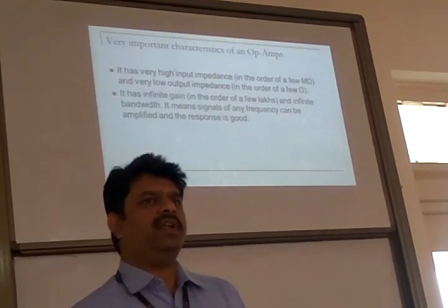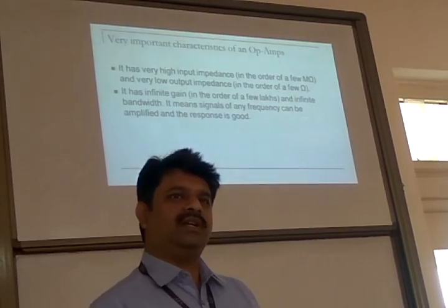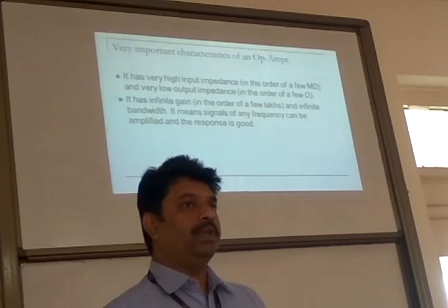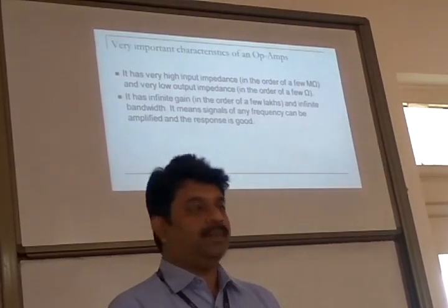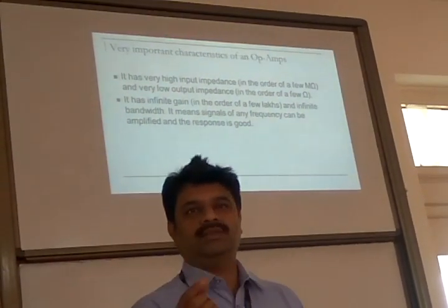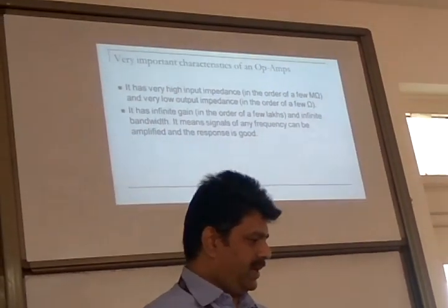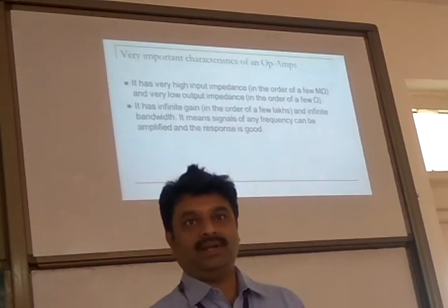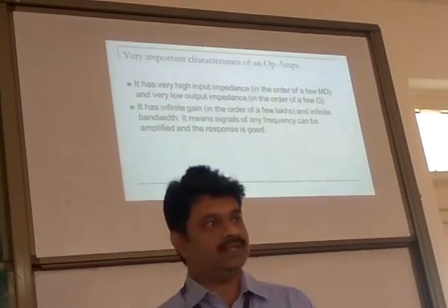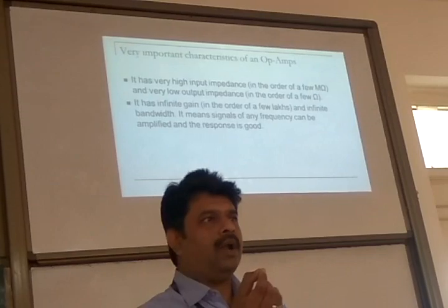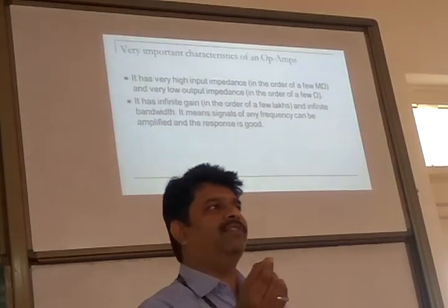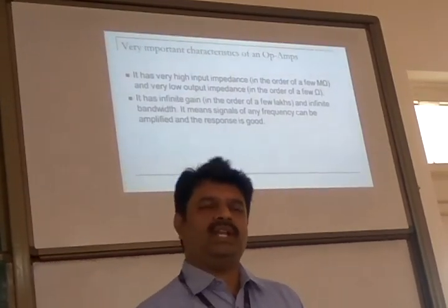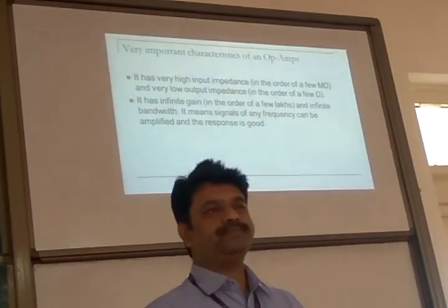Okay. What if it draws more current from the sensor? Loading effect will be there. If the loading is too high, sometimes you take a thermocouple and connect its output to a device which has less input impedance. Already there is a small 0.3, 0.4 millivolt coming from the thermocouple. Very small voltage and small current proportional to that.